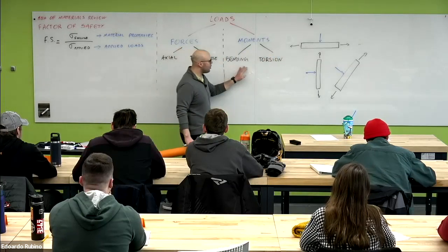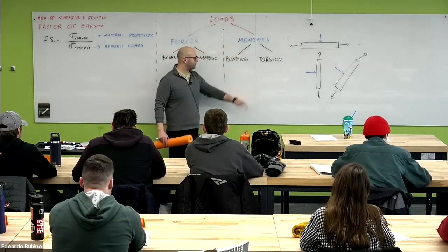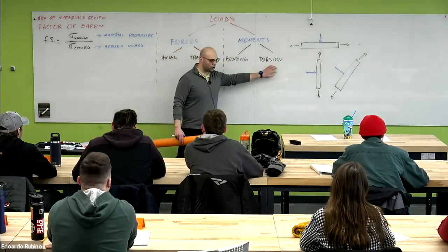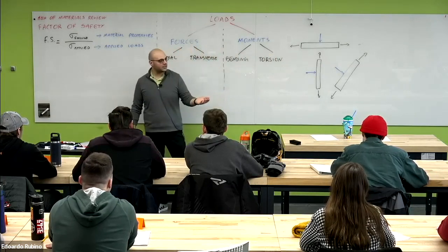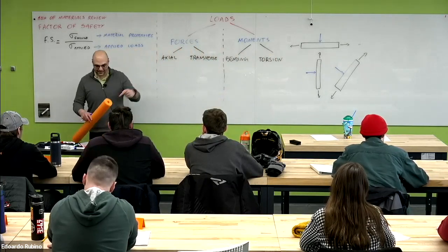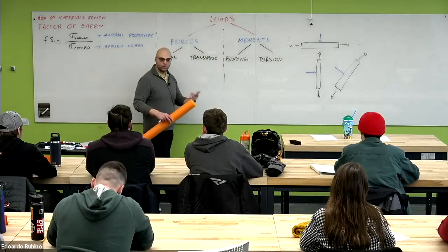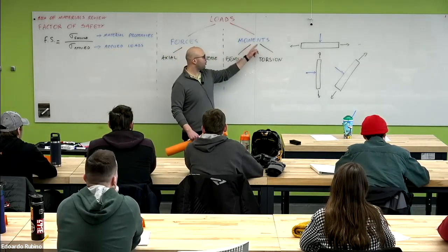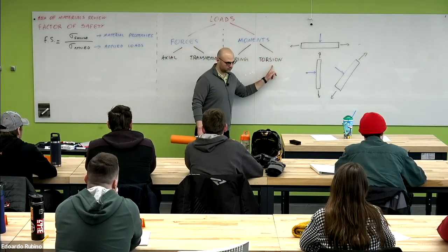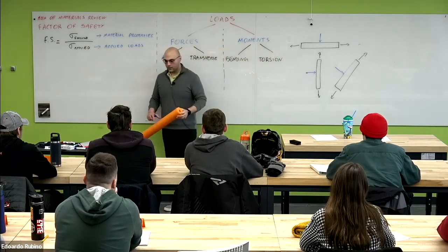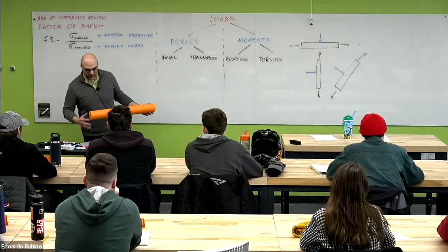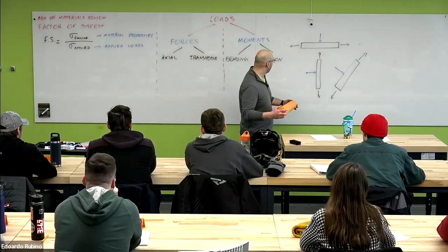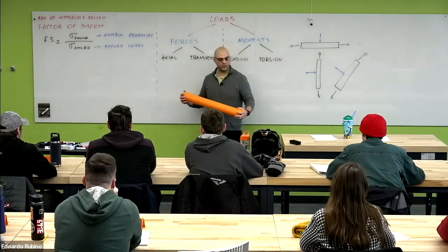So regarding the moments that we have, as we mentioned, bending moment and torsional moment. Even in this case, we can use the axis of the beam to understand if the moment is a bending moment or a torsional moment. We have to use the right-hand rule, and we can see where our thumb is pointing.